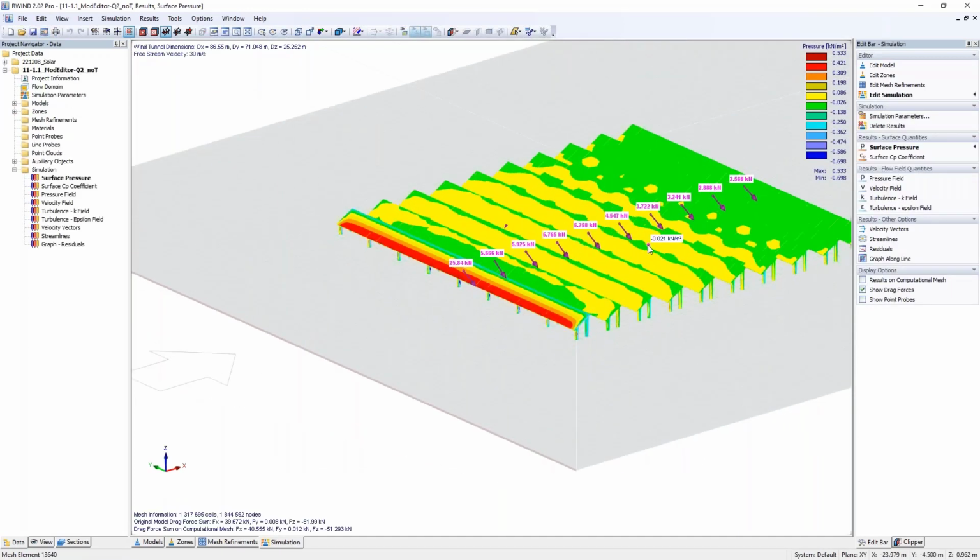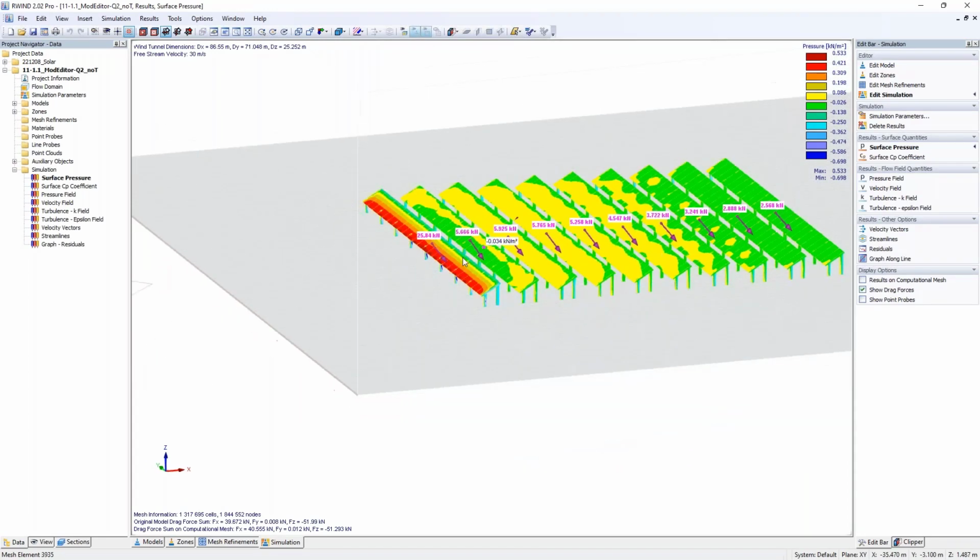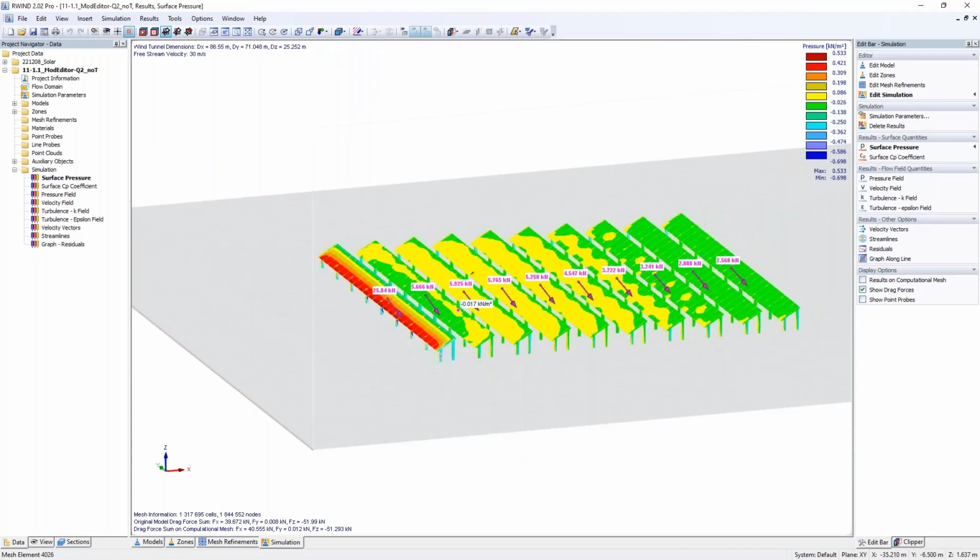And you can then later on see, of course, that for your different solar panels, you will get your drag force and the pressures, depending on the color scale. And if you check then the velocity field, hopefully it's not loading that long, you can see that the first one is working like, let's call it, a car spoiler. So it's rearranging the wind to flow over the panels. So the first one will get a higher wind drag force, of course, and the others are standing like in the shadow of them. Let's call it like this. So behind the first panel.